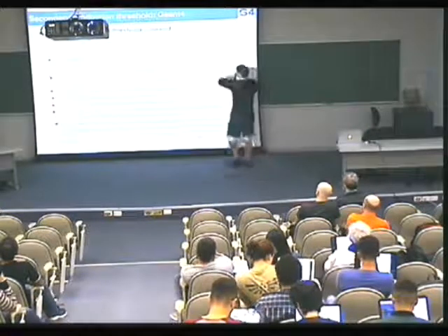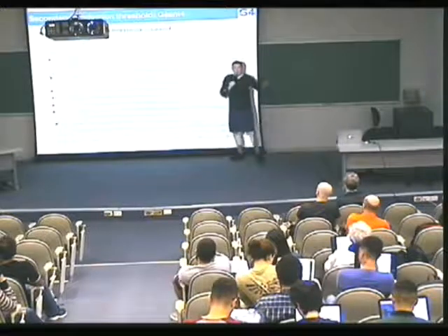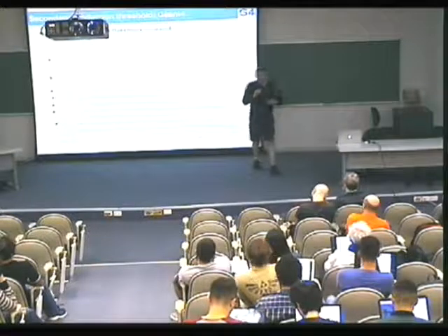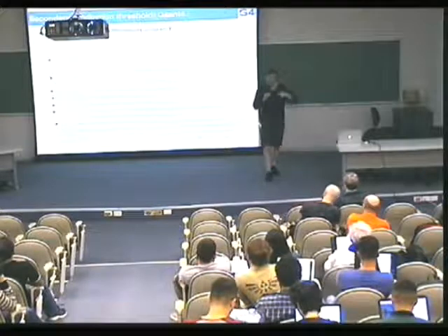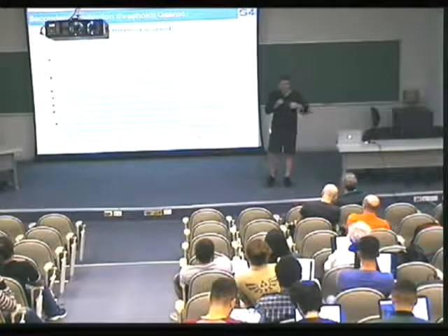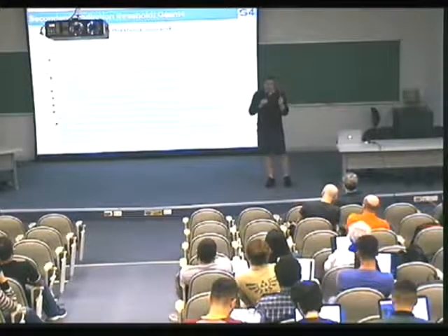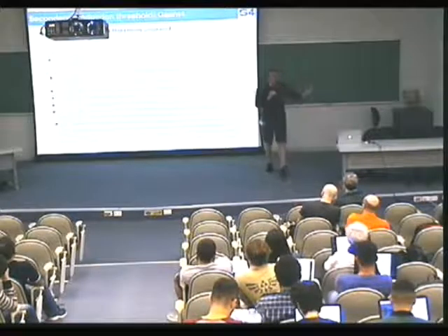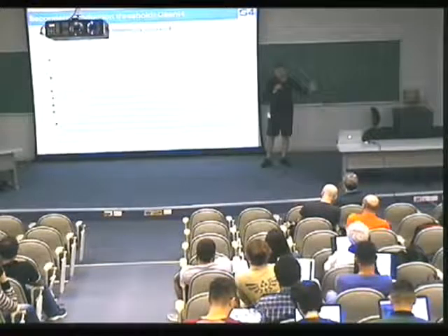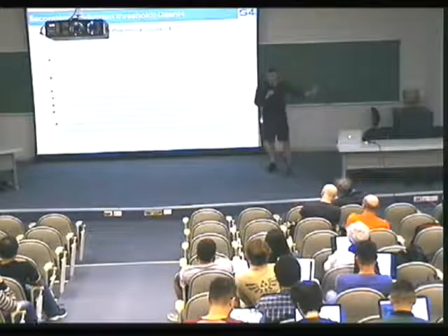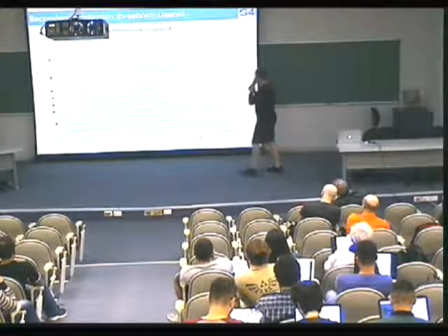And this length will be automatically translated by Geant4 at initialization to a given energy that we will use in each model in Bremsstrahlung and ionization. We will use it as an integration limit to produce the cross-section, the restricted cross-section and the stopping power tables and so on.